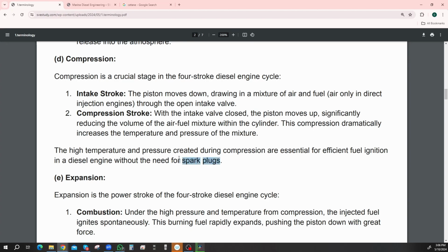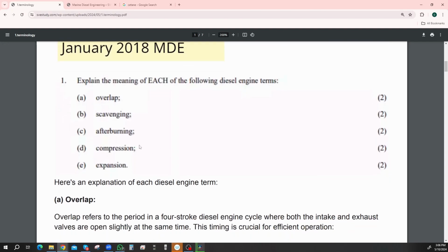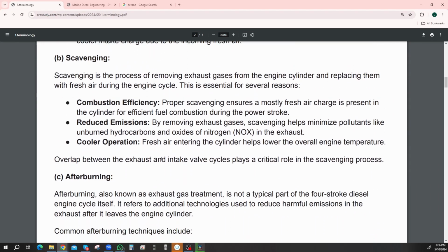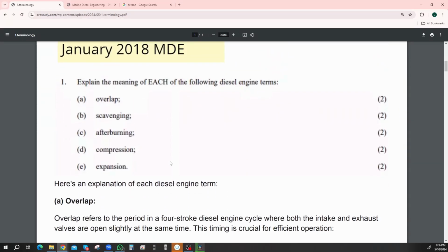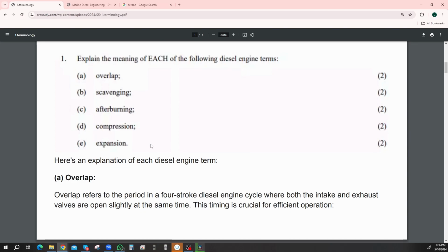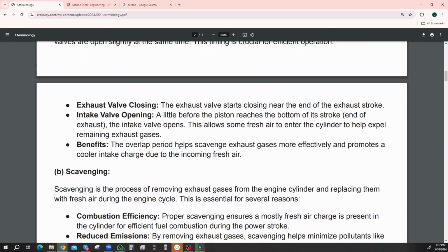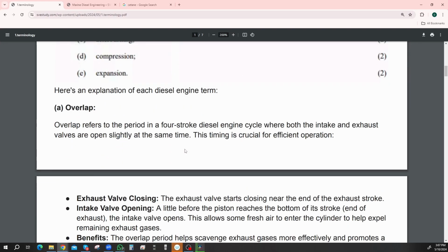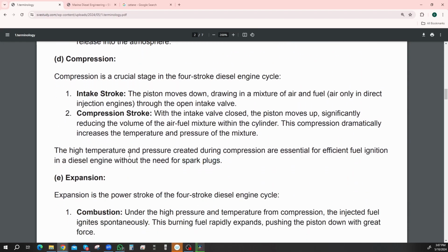Yeah, so this is what I got confused about: we're talking about diesel engines, right? So I thought, wouldn't you be mixing the air with the fuel before you inject it into the engine? And yeah, you do in a carburetor, but I think that's only for petrol engines. In diesel engines, you inject it directly into the cylinder, so it has to have air from the outside; it mixes directly in the cylinder. You inject it in there, and then we're going to get to turbochargers later on, where we're going to be squashing that air in there as quickly as possible to burn more fuel in the same amount of space. Okay, so it makes a bit more sense now. Thanks for sticking with me.